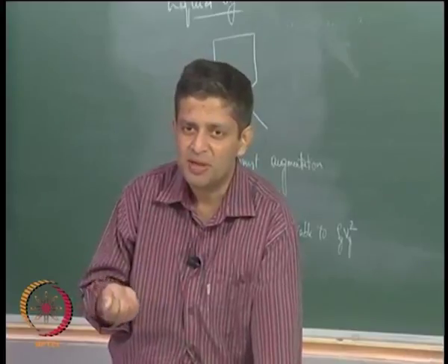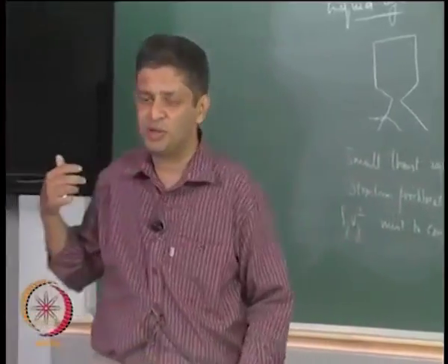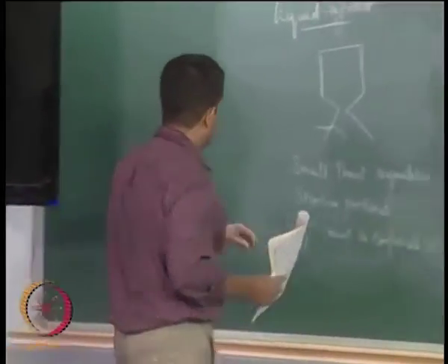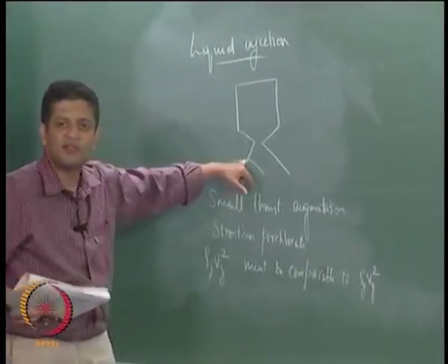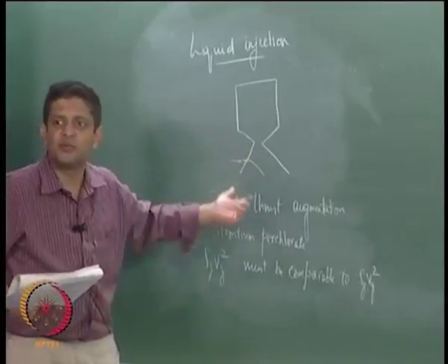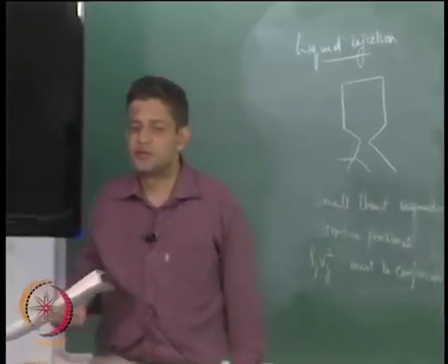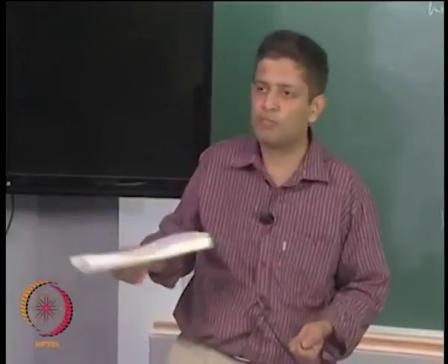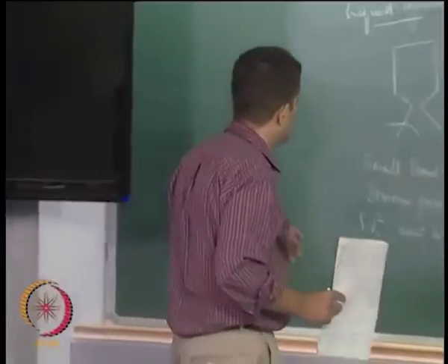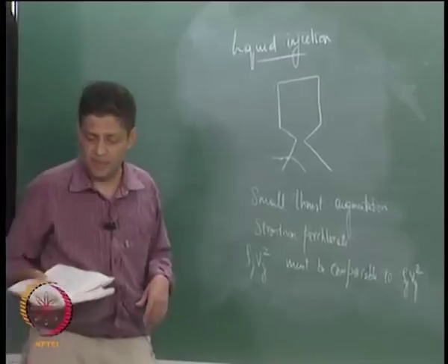So you do not want that, and therefore this kind of taking a certain bleed from the combustion chamber has not been pursued. So you have to have a large tank containing this strontium perchlorate, primarily because if it needs to be injected at some velocity, the pressure here of the jet must be greater than the pressure here. So this tank needs to be pressurized, okay, and then the liquid has to be expelled under pressure. So that makes it a little more bulky. But as I said, if you want to use gas injection, then hot gas handling is not very easy. Okay.